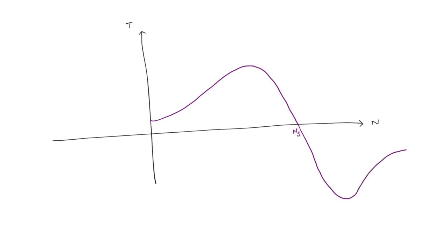Okay, so this is the motoring region. It will work as the induction motor. So we call this the motor region from 0 to ns speed, and beyond this it is called the generating region.